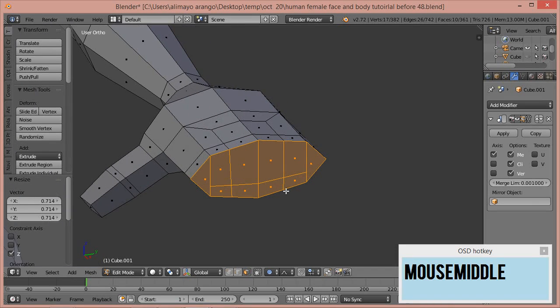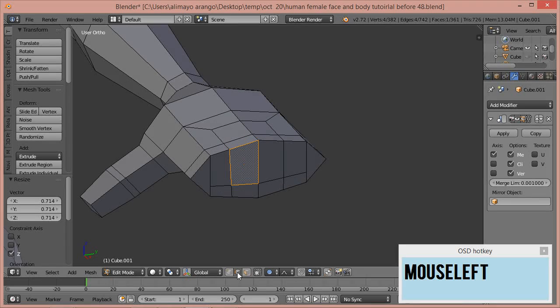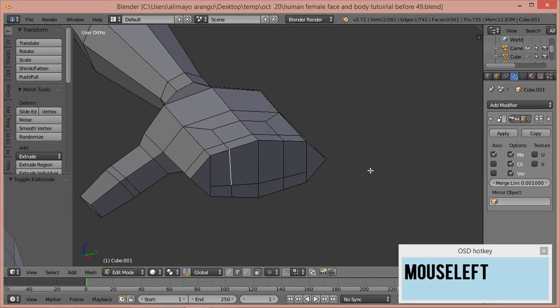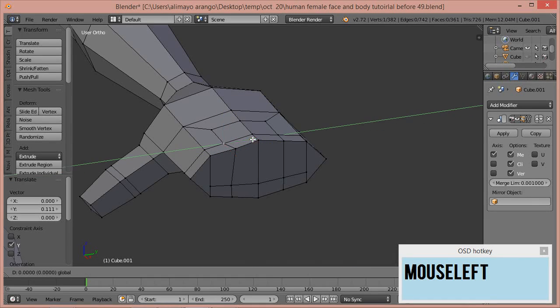Now this here I think is pretty cool. I actually came up with this a while ago. I was kind of excited to show it. Let me hit O to turn off the proportional edit tool. Actually, let me rearrange the distance here. I'm going to hit Control Space. Bring up our manipulator. I'm just going to pull this to the side just a little. I'm just giving more space for this one finger.